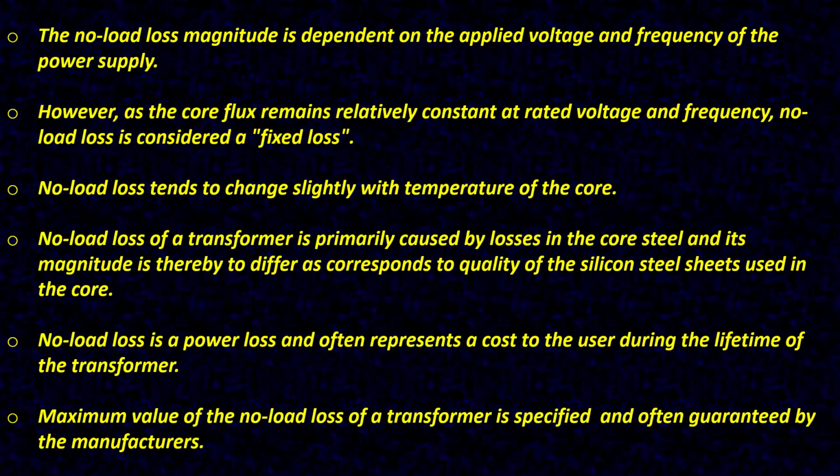The no load loss magnitude is dependent on the applied voltage and frequency of the power supply. However, as the core flux remains relatively constant at rated voltage and frequency, no load loss is considered a fixed loss. No load loss tends to change slightly with temperature of the core.